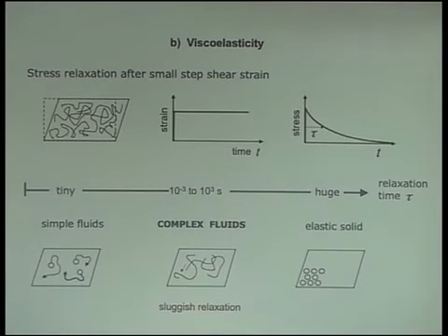And we're all used to conventional elastic solids in which that relaxation timescale is enormous and the stress effectively never decays. So an elastic solid stores stress as long as you hold it strained. And we're all used to simple liquids such as water in which the small molecules very quickly rejig themselves under Brownian motion and the stress decays essentially instantaneously.